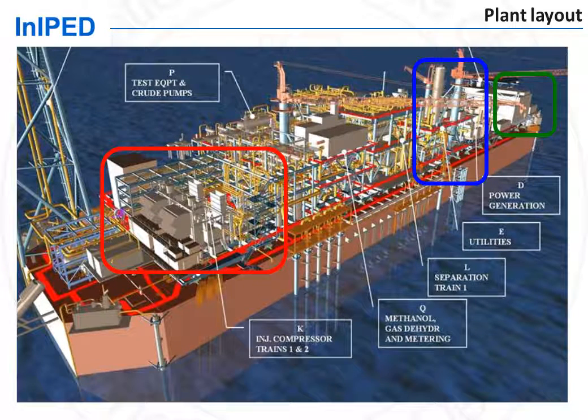Utility units are located away from process units in order that they remain operational in the event of an incident in the process unit. Manned buildings are located the furthest away from process units and in a location where personnel can easily escape the facility.